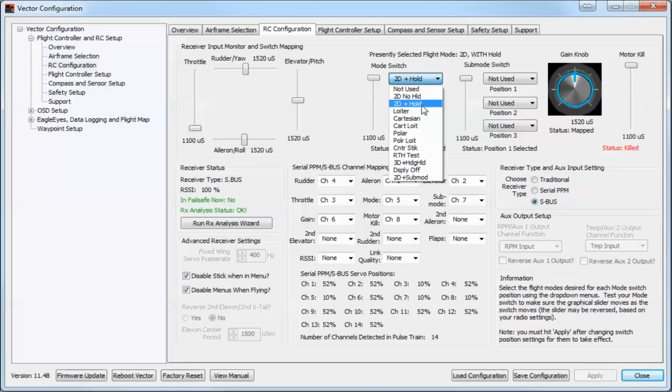The way it holds altitude is via the throttle switch. Basically, when you put your multi-rotor, let's say up to 10 feet, if you put your throttle at 50%, the Vector will say, okay, I am supposed to stay at this height. So it sees that your throttle is in or around the 50% mark, so it says, right, via my barometer, this is where I need to be.